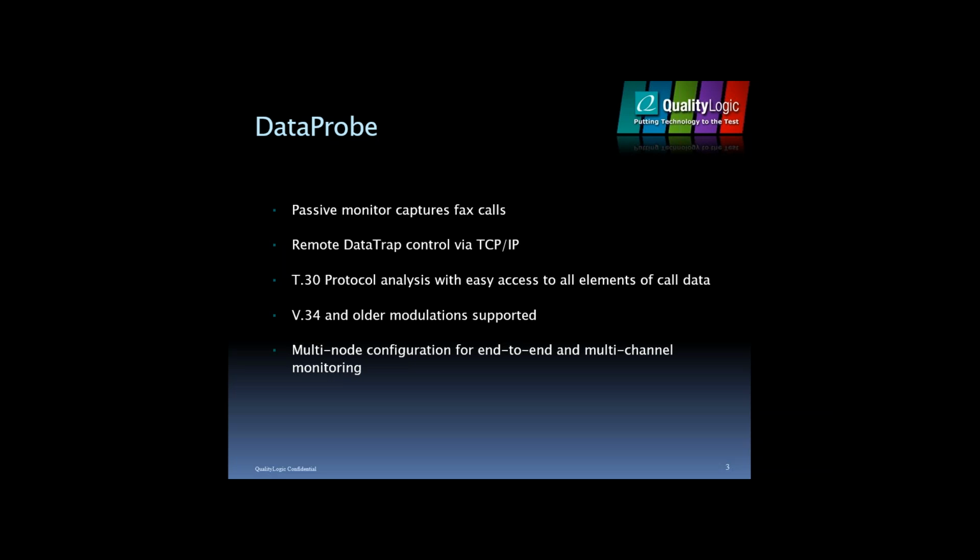Again, DataProbe is a passive monitor that captures fax calls. What this means is that it will literally listen to the communications between a fax terminal and its connection and absorb the analog signals going back and forth between the terminal and its remote terminal, and also analyze these for T30 content and present that information to the user.